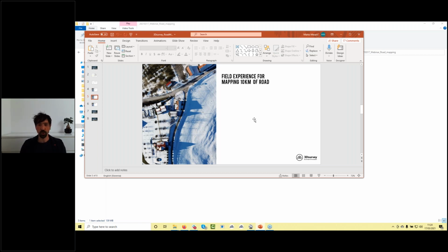Okay, I'm not sure if you recognized, we had turned off the obstacle avoidance sensors. This was because we had a lot of issues a long time ago with the low sun, and if the drone flies directly toward the sun, the sensors figure out, okay, it's some kind of obstacle, and the drone stops, noticing there is something, but the drone was at 80 meters. So after a few projects, we figured out that the sun is a problem.